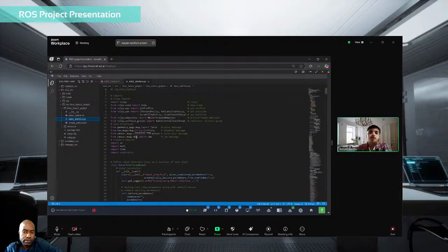This script will create a ROS2 node and publish parameters like distance and odometry to the ROS framework. Then this shell script will interact with that ROS2 node and manipulate parameters like speed, when we want to move or when we want to stop.